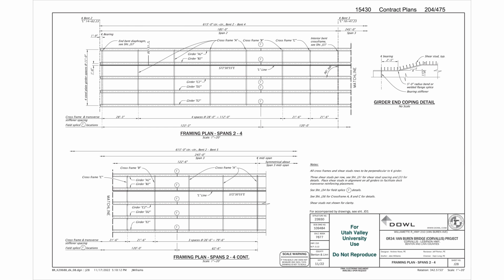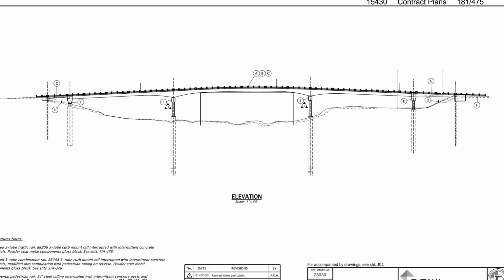Redundancy can be designed into a bridge, for example, the new Van Buren Bridge, by having multiple girder lines. So if it's more than two, we're calling it redundant, because that way if one girder fails, the other ones can carry the load, and then the bridge can be closed and made safe again to use. So that's load path redundancy there, and also the system redundancy of just having the steel girders go all the way across the river, supported in multiple internal locations, so that if one part fails, that girder line will actually help hold the bridge up.